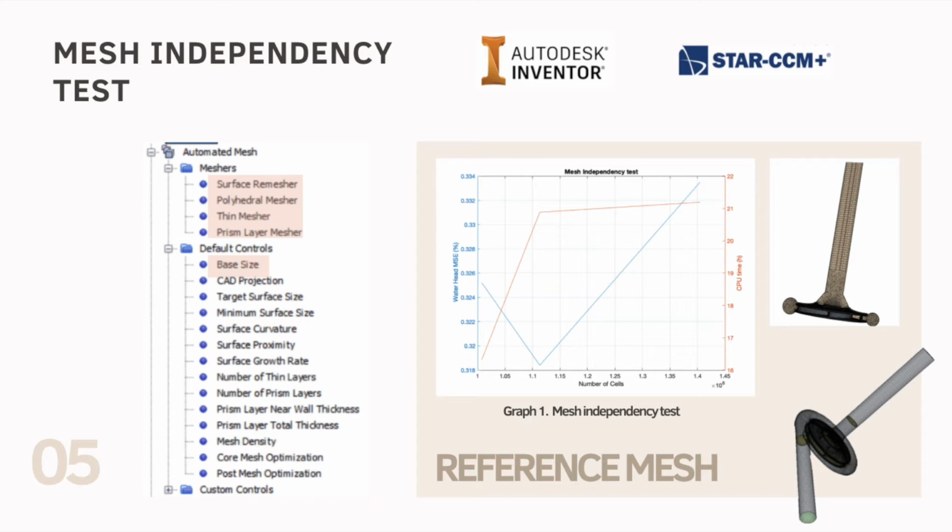After having performed the mesh independence study with water, having the results of the number of cells, the computation time for each mesh, and calculating the error of the total head obtained with CFD compared to the manufacturer's head, it can be observed that the error in the reference mesh was the lowest compared to the other meshes, and that the computation time increases as the number of cells is greater. The reference mesh was selected to perform the next simulations because we prefer to have greater computation time than a greater error.